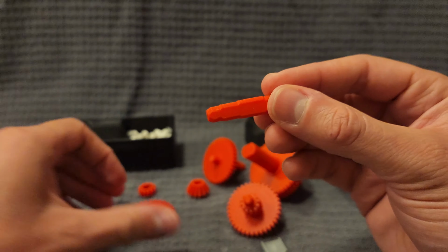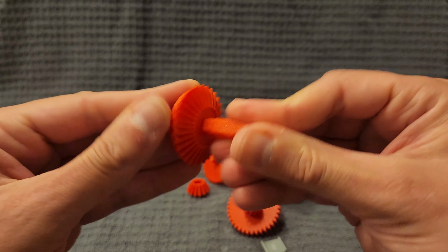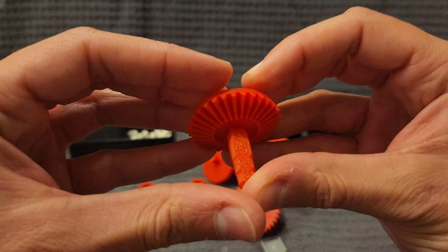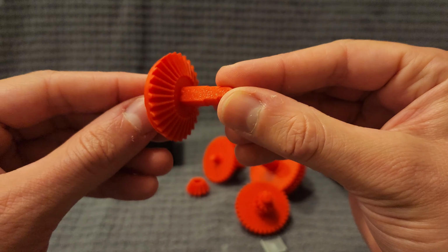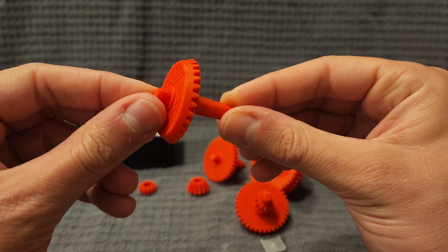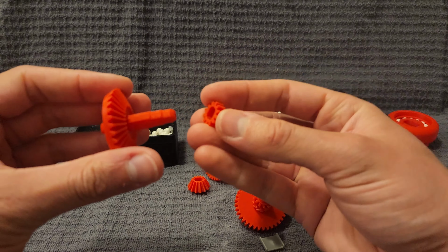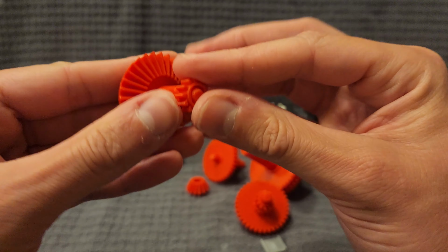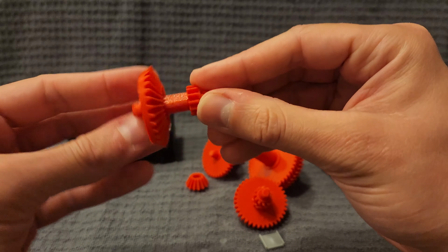It has a wider portion on which you can put a gear, and that is destined for the bowl gear, as you can see here. Make sure it goes all the way in. Again, I have to push a little bit by resting on the table, and it goes all the way in. Then you can put on the last spur gear on the other side. Again, with the bump facing towards the end of the shaft you insert it from, as such.